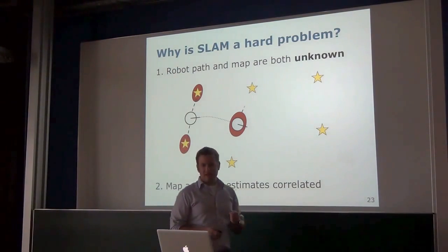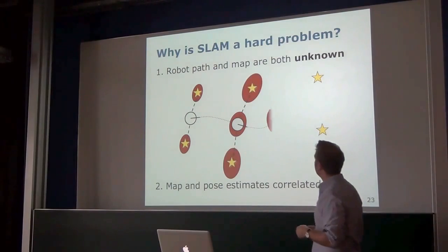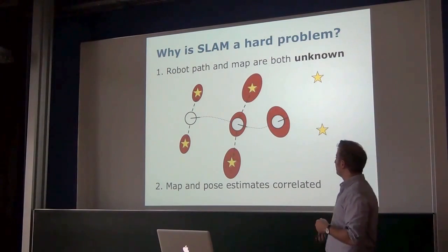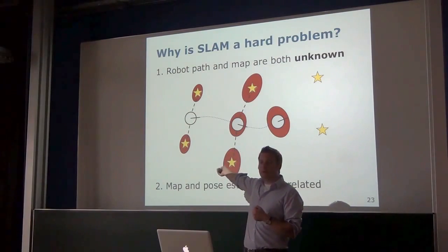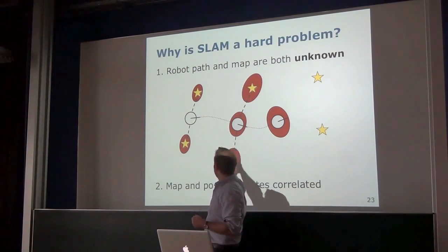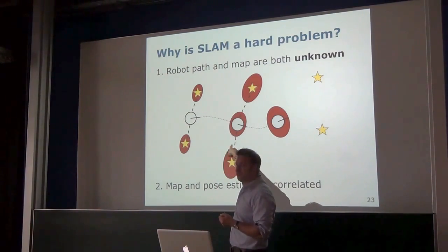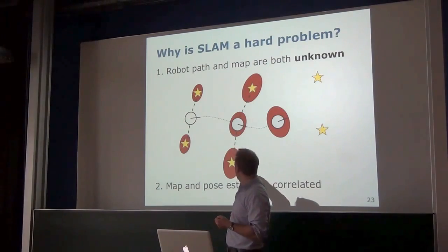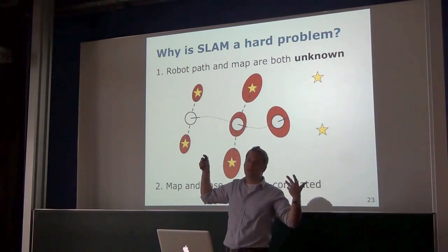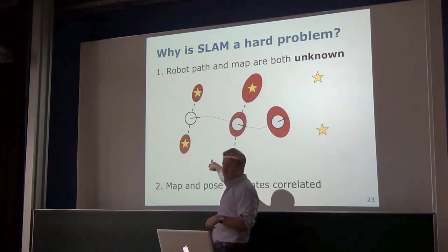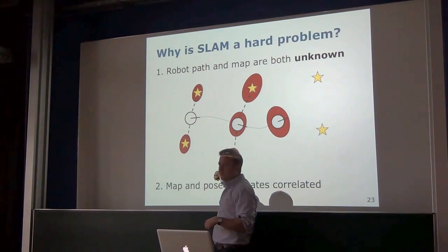Okay, next thing the system does is, again, it does observations, observes those landmarks. So the global uncertainty of this landmark is now bigger than these guys over here, because the robot had an initial uncertainty about its own pose. And it says, I don't know where I am exactly here, and I additionally have to add my measurement uncertainty, so this ellipse gets bigger. Okay.